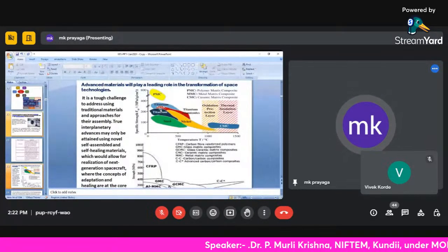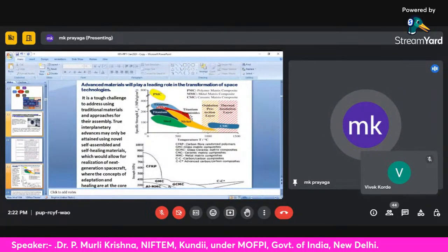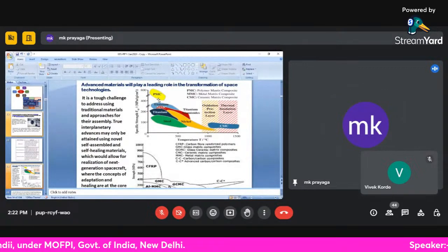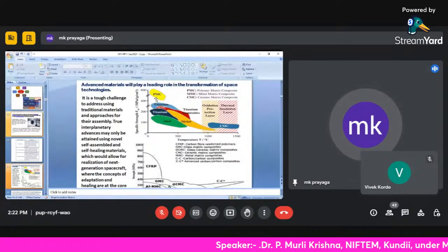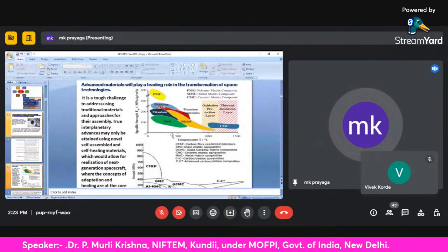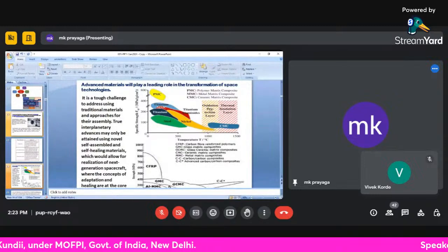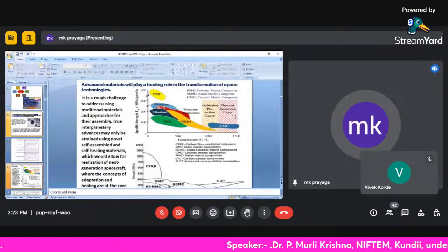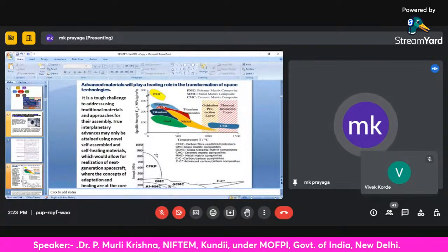And there are metal matrix composites. This is also very much used in automobile applications. Metal matrix composites, titanium for high temperature applications, and even polymer matrix composites (PMCs). PMCs at low temperature give very high strength and lightweight compositions. But if you need very high temperature stability, we need to go for nickel-based compositions. And even oxide materials and thermal insulating layers, composite coatings are required in these compositions. So this is the chance for material selection.